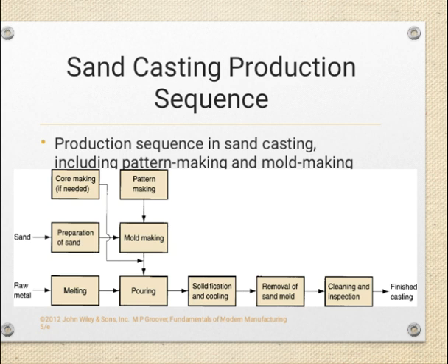Then we leave some particular hours, days or weeks according to the time solidification and cooling take place. Then removal of the sand mold takes place. After the removal of the sand, cleaning and inspection of the product which is obtained as a result is done, and the casting process is finished.